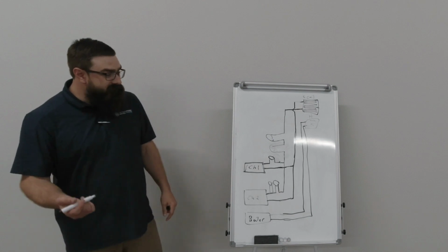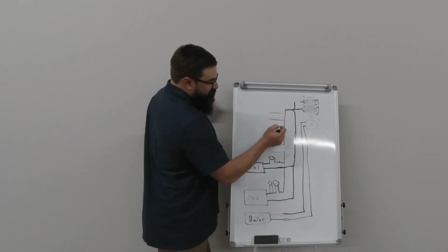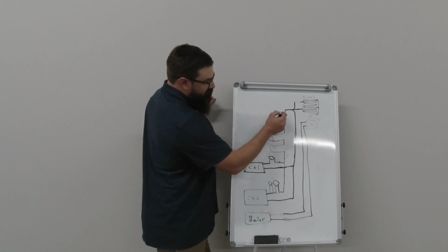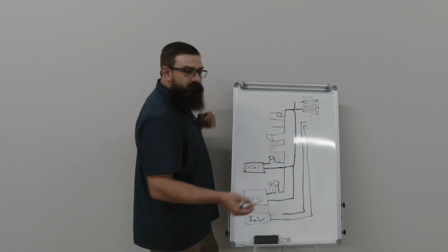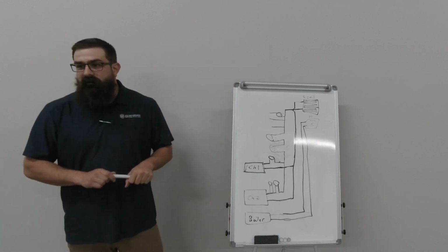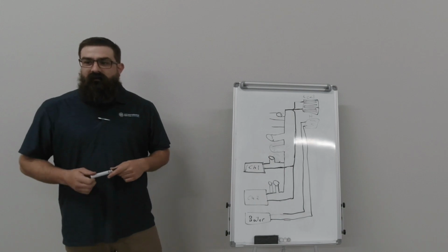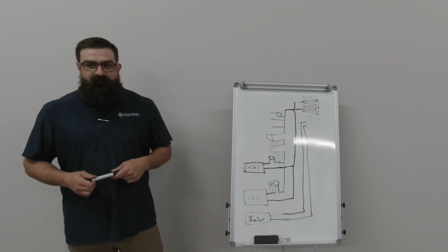And then if you get even crazier, you can get booster pumps. Like if this is a multi-story building, way up here on one of these floors, you could have another pump that helps circulate and keep the pressure even throughout the entire building. Those are fun when you have to find those and they end up in some broom closet in a hallway that nobody remembers is there.